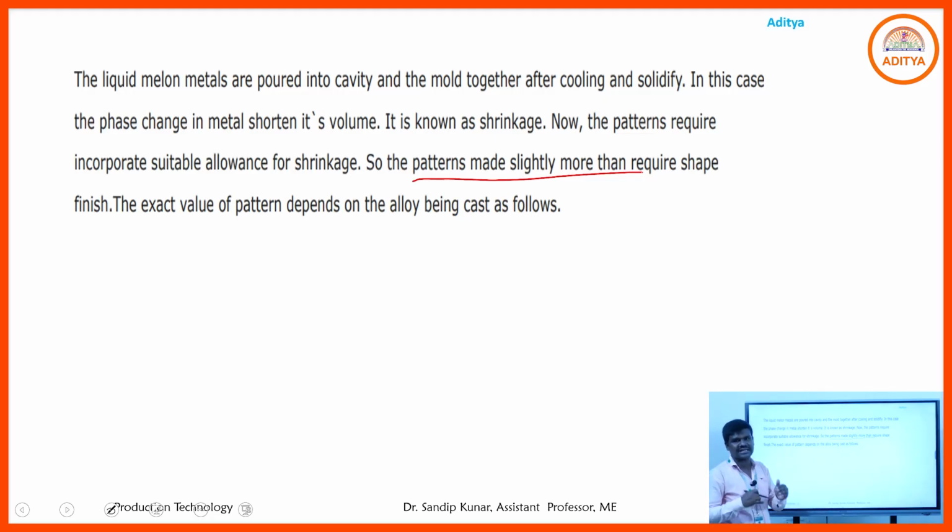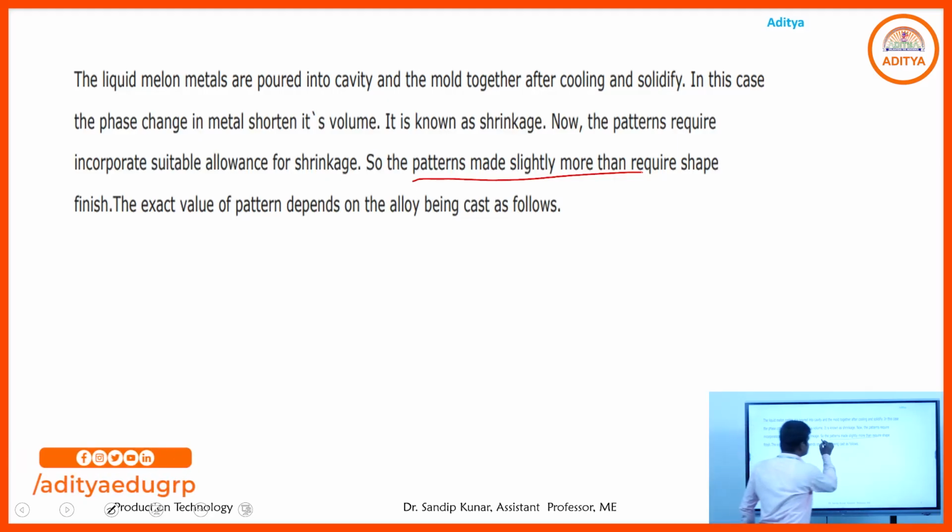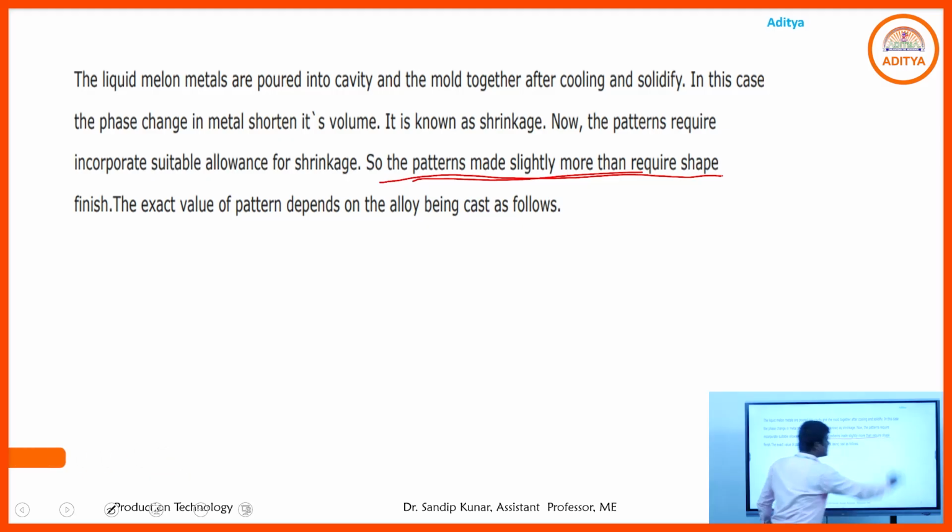If we take a bigger pattern, a bigger cavity will be formed, and after solidification the actual product will be produced with accurate dimensions. So that is the main issue: patterns may be slightly more than the required shape.